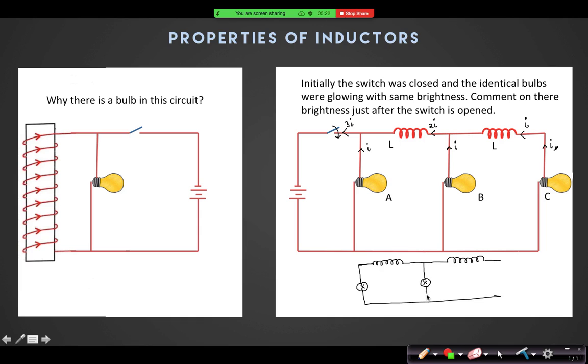That first we have to see. Because this is a closed loop, I have not actually broken all the loops. Two loops are still there, so currents can flow in the loop. And the current in that inductor was initially I, so that will try to remain I. And this current was initially 2I, that will also try to remain 2I.